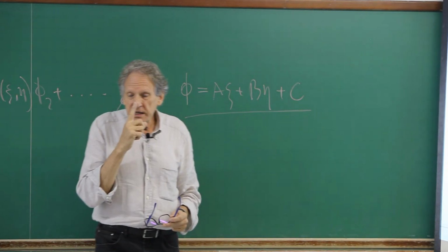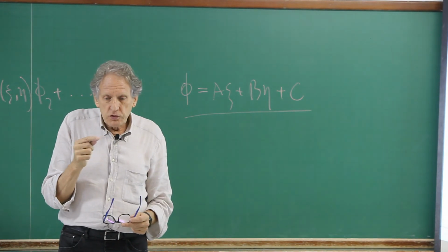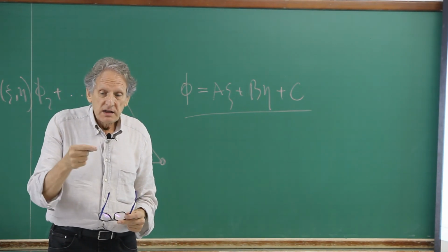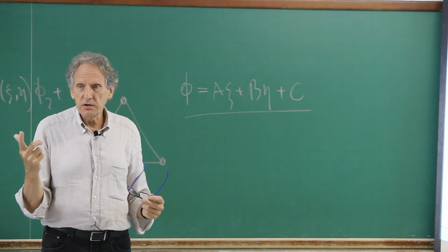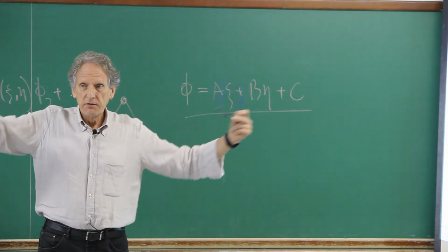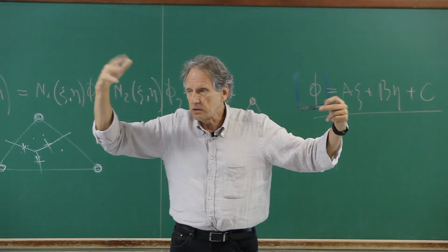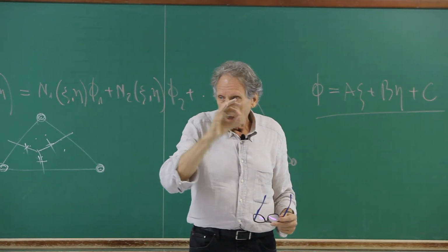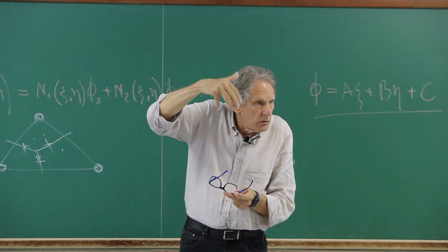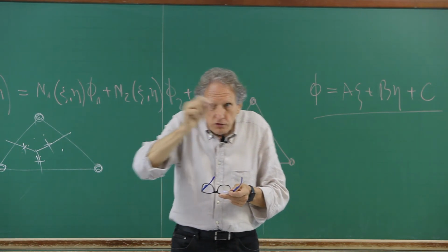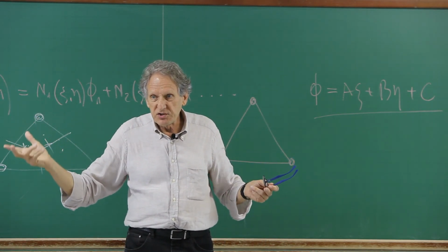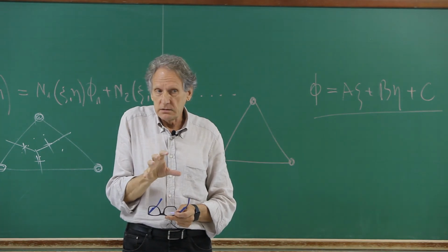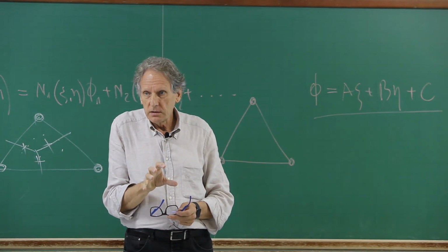So it's a line in this big, large grid of the reservoir. It's not easy to solve in detail the flow around the well, because if you have a grid which is 50 by 50 or 30 by 30 or something like that, how can you calculate the flow close to the well precisely? Then you have to refine close to the well.